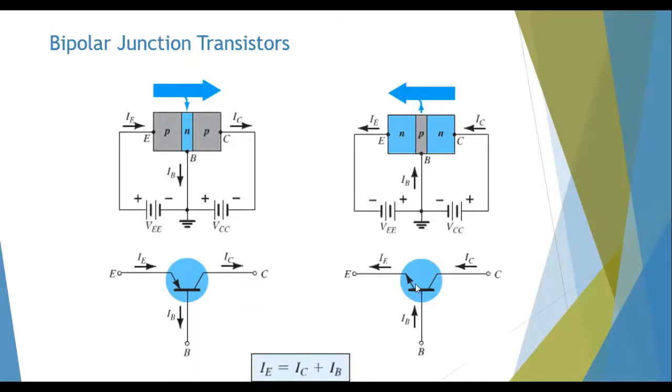This is why for an NPN transistor, you would see the arrow going into the emitter, because what is flowing away from it are actually electrons. But you have to reverse the direction to show the direction of positive charges, because by convention, current is flow of positive charges. So for an NPN transistor, the arrow would come into the emitter. That's all. Yeah. So I hope it is clear. If not, I can explain again.